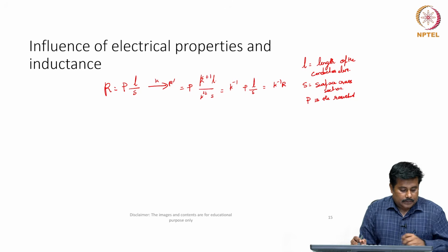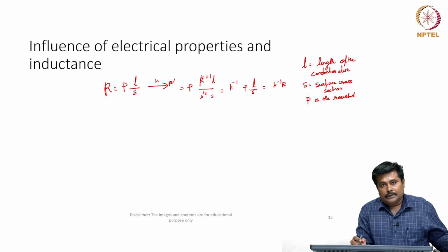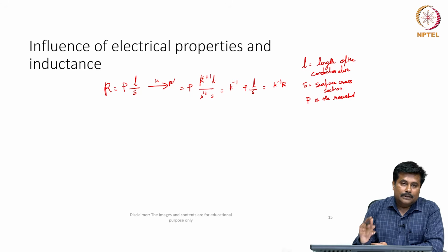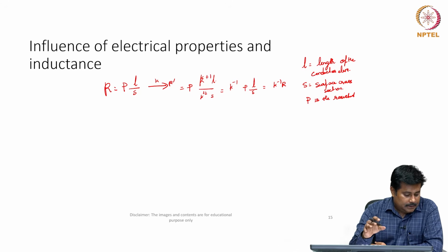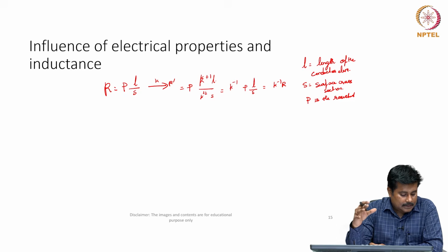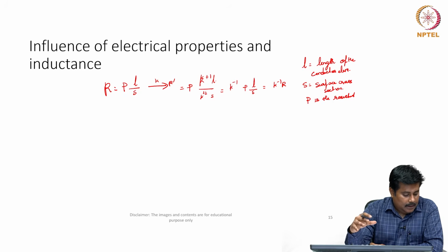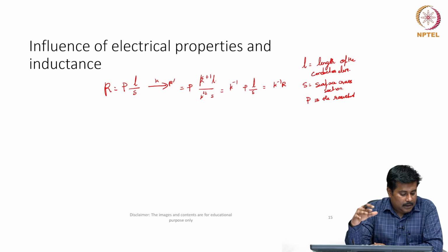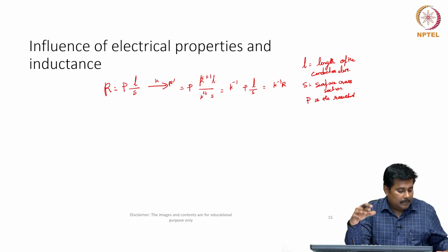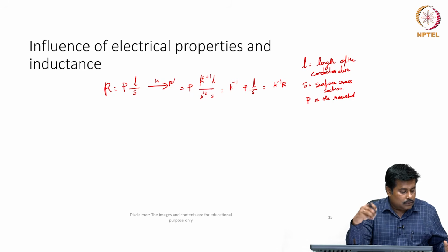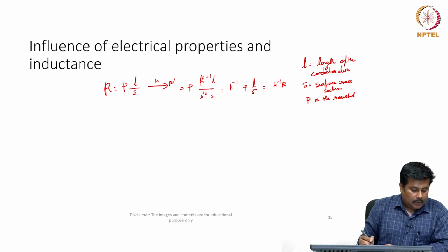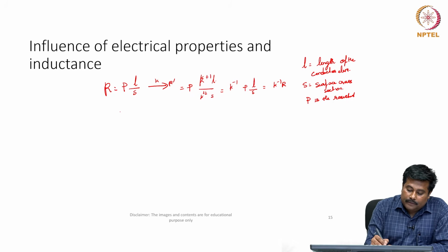In particular, the scaling law k minus 1 basically indicates that the resistance increases with scale reduction. It should be stressed that we are making the assumption that electrical resistance can still be described with the classical law. At nanometer scale, quantum effects start to be observable, and therefore the law above is no longer suitable. Similarly, we can also estimate the scaling law of the capacitance.